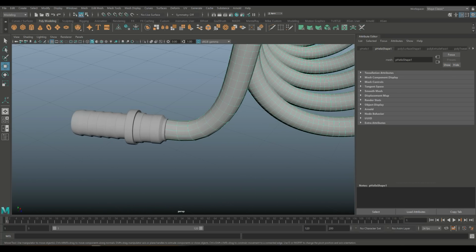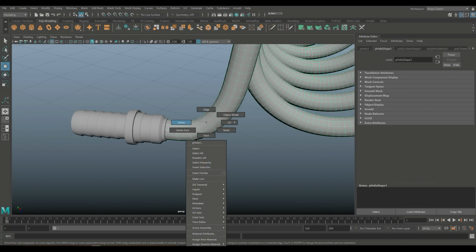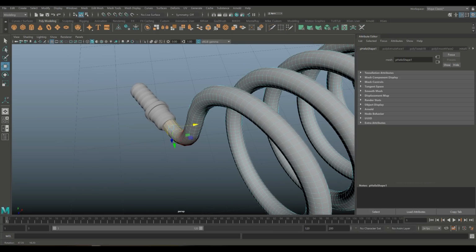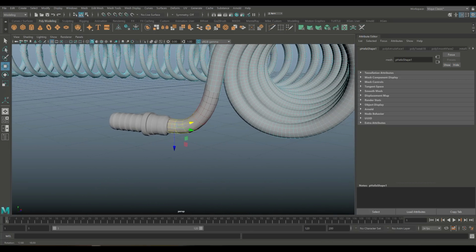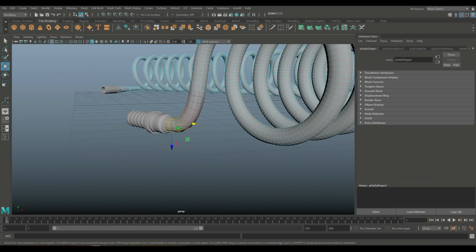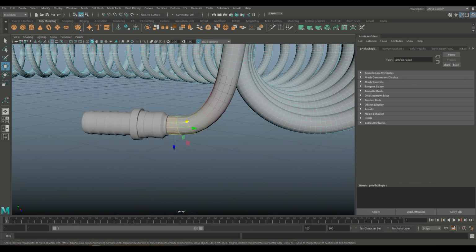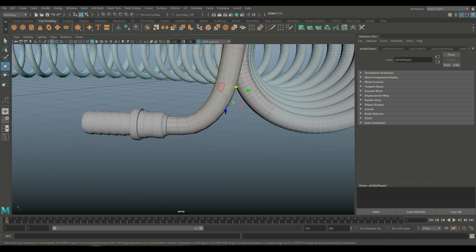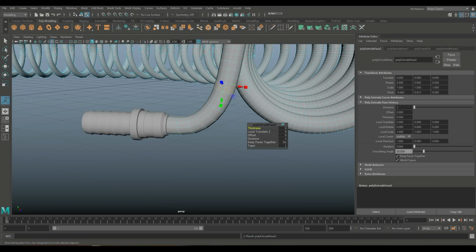Better. Okay, then we're going to go in here as before. We're going to go to face, click and shift double click, hold down B and shift and drag. And of course this is already quite thick and I don't want to make that any bigger, so maybe what I'll do here is just go into face, turn off B, Control E to extrude,